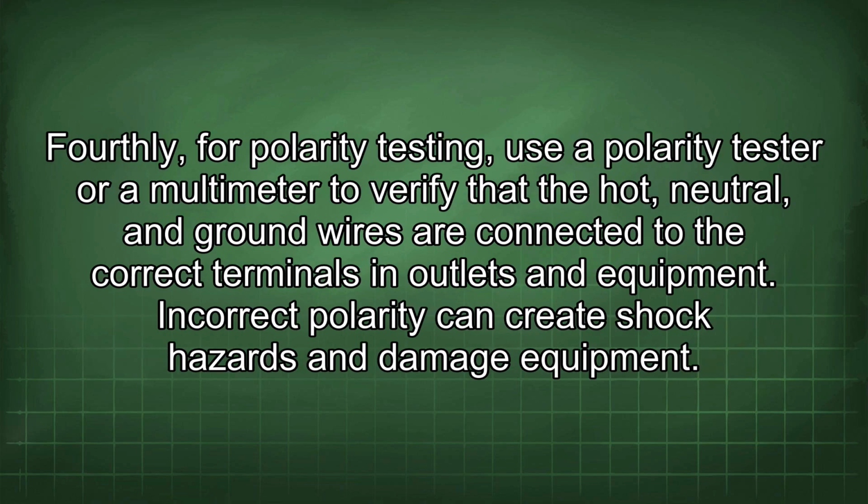Fourthly, for polarity testing, use a polarity tester or a multimeter to verify that the hot, neutral, and ground wires are connected to the correct terminals and outlets in equipment. Incorrect polarity can create shock hazards and damage equipment.